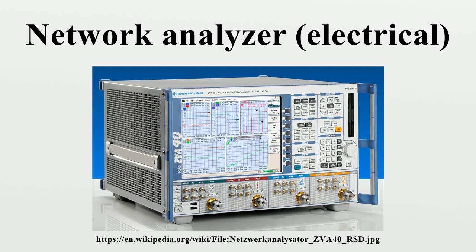The SOLT calibration method is less suitable for waveguide measurements, where it is difficult to obtain an open circuit or a load, or for measurements on non-coaxial test fixtures, where the same problems with finding suitable standards exist. TRL. This technique is useful for microwave, non-coaxial environments such as fixture, wafer probing, or waveguide.